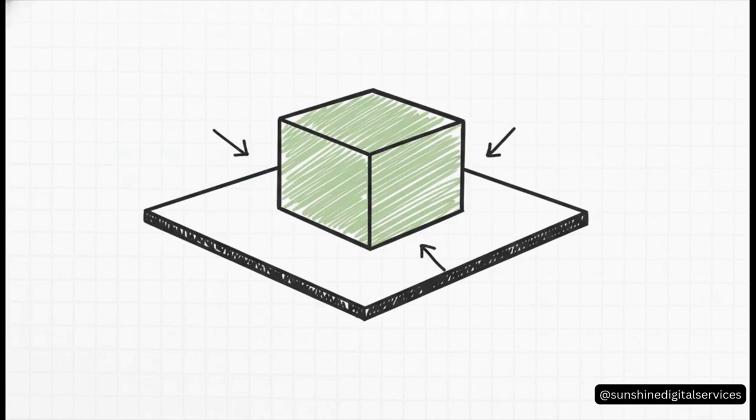Next, right on top of that ground plane, we draw a 3D box. This is our substrate, the filling of the sandwich. It's an insulator. And just like we talked about, we go into the material library and tell the software this box is made of FR4, that standard circuit board material.